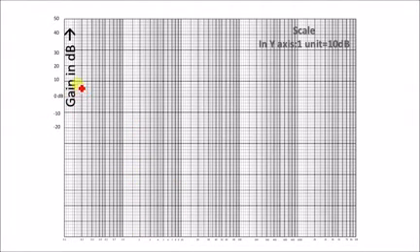So I have chosen 0 dB is this line. Okay, this is 0 dB I have chosen. Then if I go up I have a positive, then if I go down I have negative. So for 1 unit I can change in y-axis, 1 unit is equal to 10 dB. So here 0 to 1, this is 1 unit now, 1 gap equal to 1 unit. So 10 dB, 20, 30 likewise.